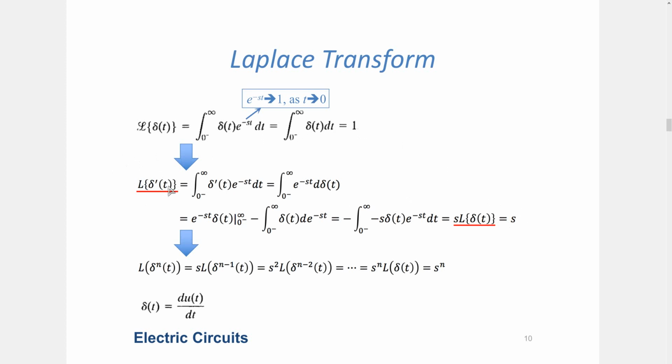So we got rid of the integrals and the differentials, but we end up with a regular expression like s. This is where the true power of the Laplace transform comes. And we use this a lot when we are dealing with circuits, especially AC circuits and circuits that we would like to explore the time domain and frequency domain behavior.